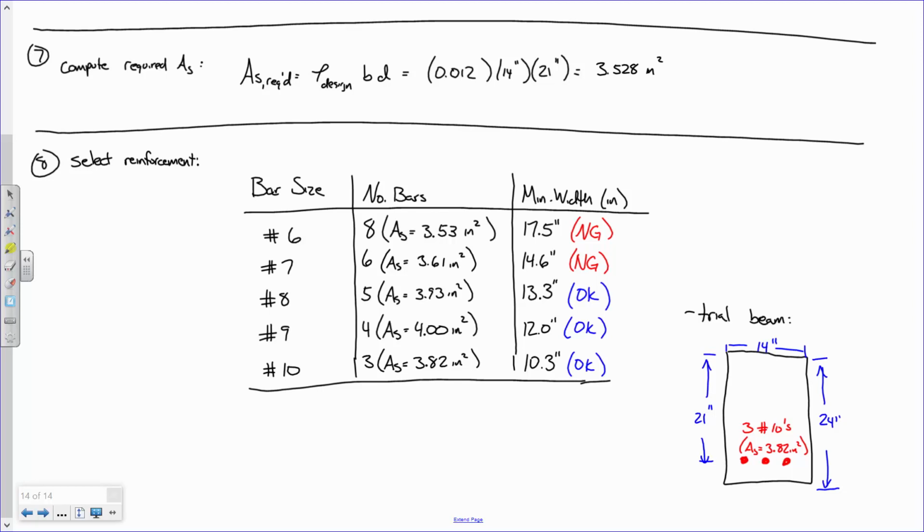But we're not done with this problem, okay? Because there's something that we got to go back and check. We got to go back and check those assumptions, right? We assumed the beam self-weight, okay? We assumed what our phi value is. We don't know that that's right. We arrived at this beam based on guesses. We have to check those guesses. So step 9 is to analyze the beam. Okay? Does that make sense? Any questions? All right. Can I move on to the next panel?